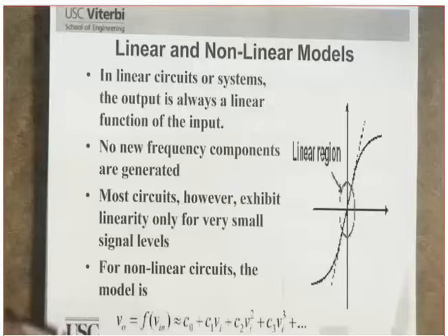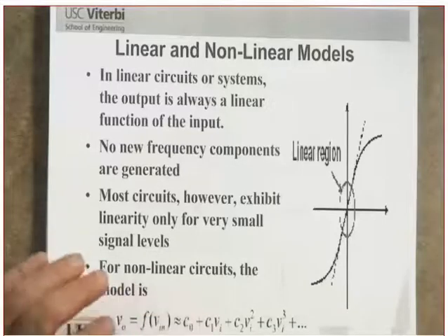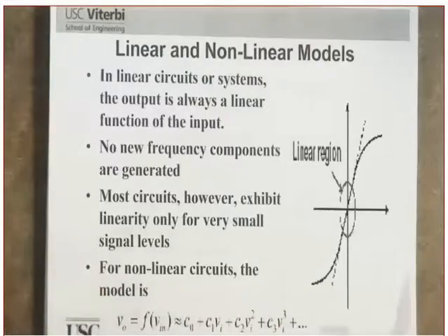There's no other way around it if you are going to use modulation schemes that are non-constant envelope. If you use non-constant envelope with nonlinearity, which I'll show you later in detail, all of these side lobes that you got rid of when you did the channel select at the transmitter will reappear again.